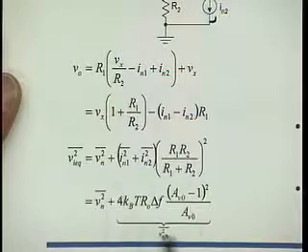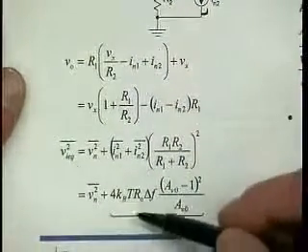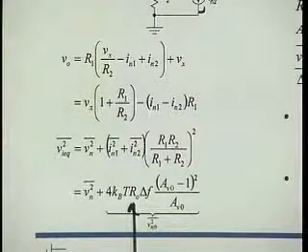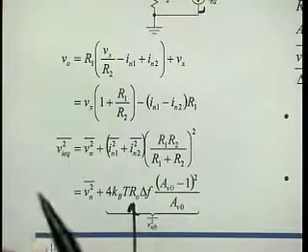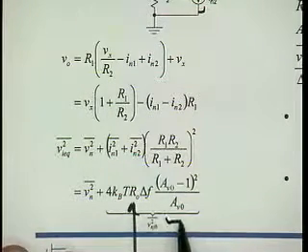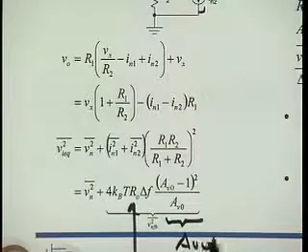And so you have an expression here. It depends on the value of the resistor, and also it depends on the gain. Well, apparently, even though we are looking input-referred, if I want to make a high gain amplifier, then I still get a little bit of extra noise. Whatever. This factor here is approximately equal to AV0. Right?